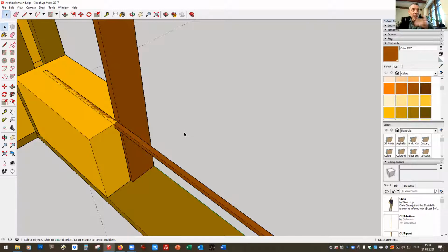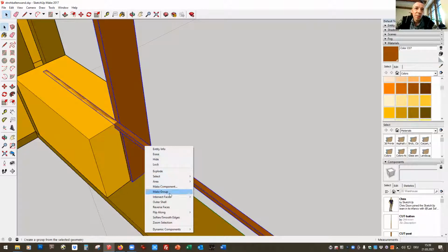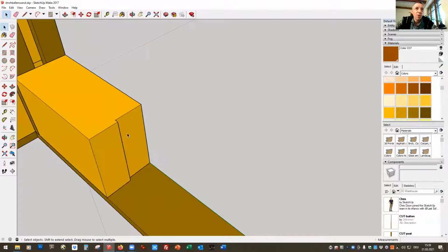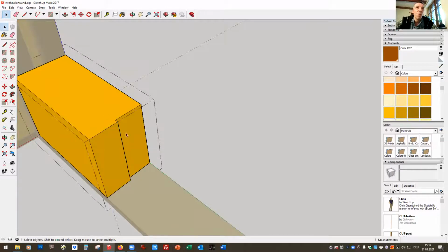In reality, we really cut out the surface here, the surface of the bale, with an angle grinder, a round chainsaw, or with a cutter or alligator or something like that. To cut out the bale here for this notch, it's best to hide these both elements. You just hide them, and then you see your bale. And what you do is you open your unique element, the straw bale, and add a square, which is 2.5 by 2.5 centimeters here on the surface.